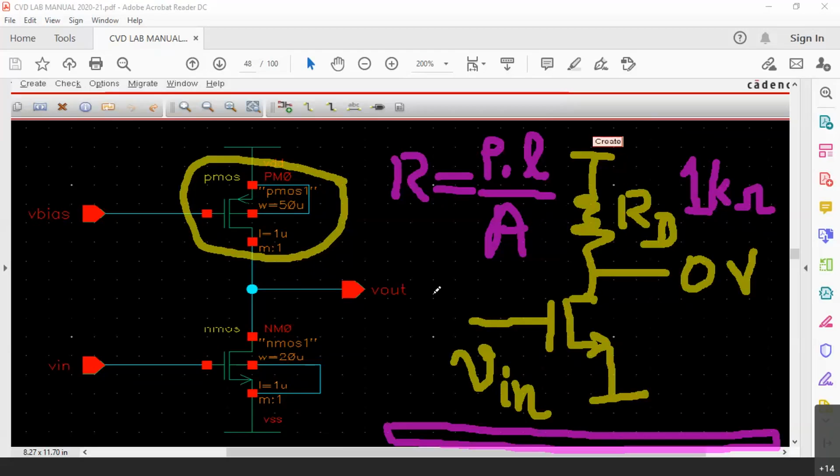You would have seen that big transistor called 2N3055 mounted behind the power supply, so that the heat with the transistor will be easily dissipated to the atmosphere as well. So the life of the transistor is going to be increased. Of course, the transistor also will have the heat sink with it.